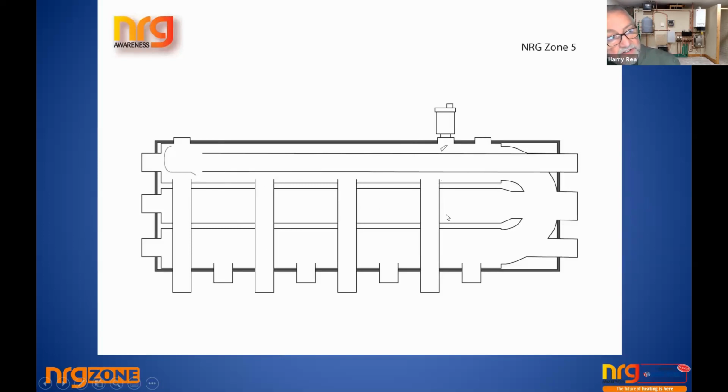So again, each zone now, if you go back to the first diagrams, has full access to the 2.5-inch header to take away whatever water, there's no conflict. And the 2.5 inches is made up excluding the volume of the pipe on the inside. So it means that it's extremely open for the water to reach. But another thing, the boiler pumps are assisting to push the water towards every open pipe. So instead of there being a conflict in the system, the water all flows in the same direction. So it works very, very smoothly if there's one boiler or two boilers. Same applies on the return.